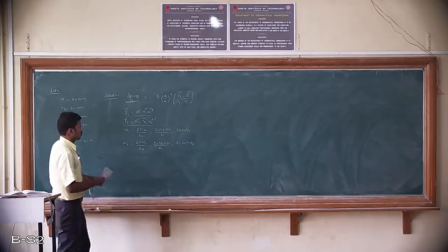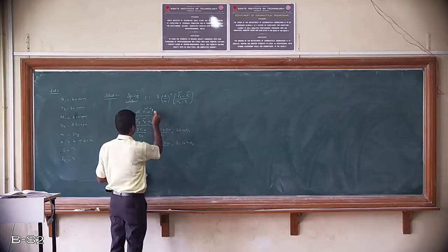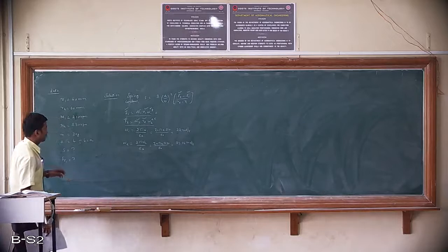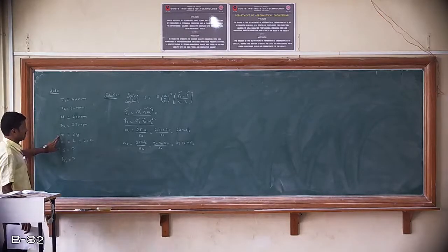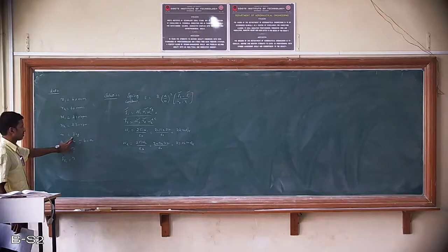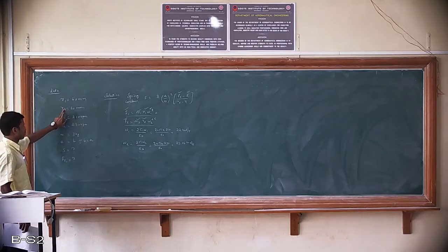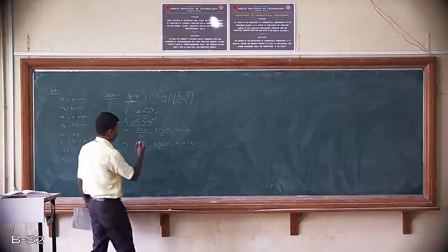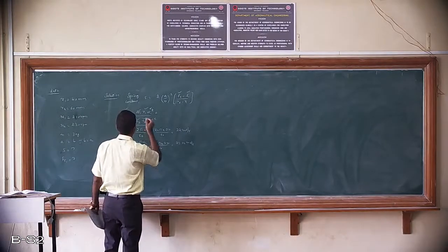So it means I got the value of omega 1 and I got the value of omega 2. Now substitute the value of omega into the governing equation of m1 r1 omega 1 square. As the mass of the ball is going to remain the same, for m1 and m2 we have to take the same value of the mass. The mass is not varying, but the r1 and r2 values are varying, and omega 1 and omega 2 values are varying.